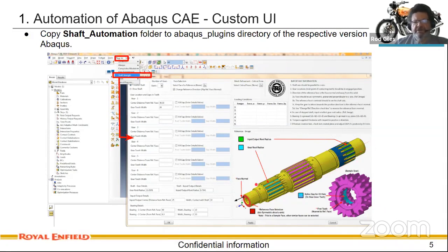And then also we have a dialog box to apply the torque requirements for each gear. So we can actually carry out a run for all the torque applied for each gear as a separate load case. So that's how the dialog box looks. There's other options. We can look at the number of gears that the gearbox might have, if it's a 4, 5 or 6 speed gearbox, and so on.